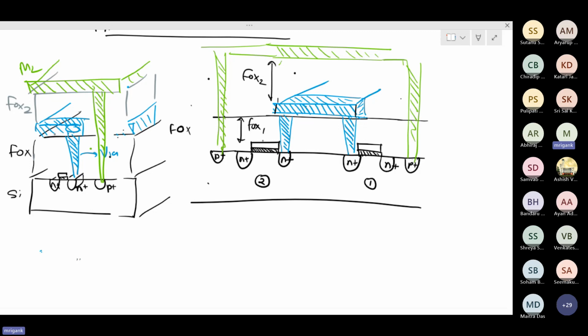So the main motivation behind giving you this overview of fabrication process was first to give you an idea of how the VT, the threshold voltage, will be dependent upon some of the fabrication parameters like the oxide thickness, work function, doping density, and so on. And second, the physical structure, actual connection between the MOSFETs in a chip, how will it be formed using these multiple layers of metal connectivities with the underlying silicon transistors. So this idea you should have.